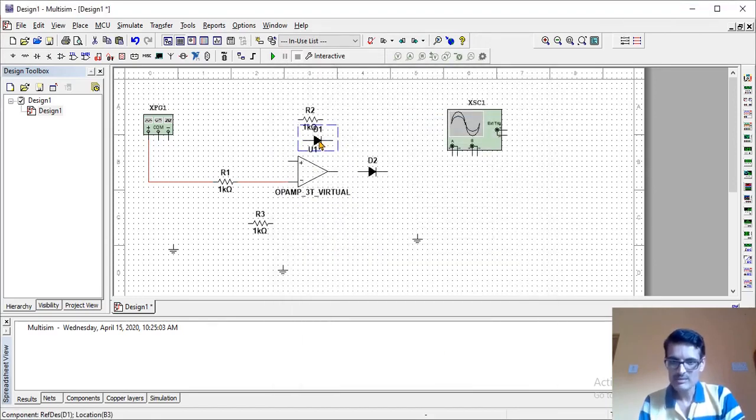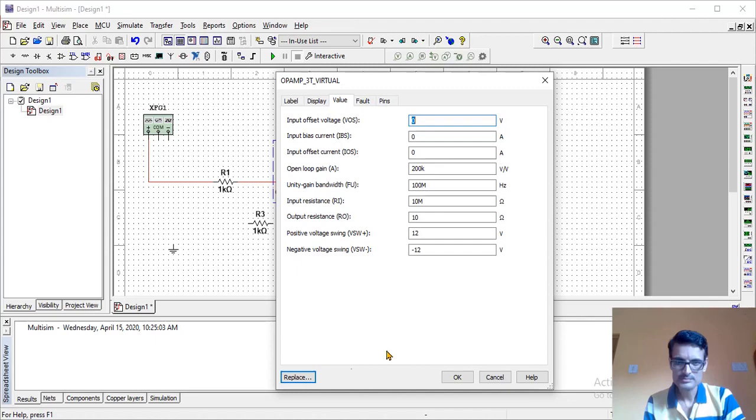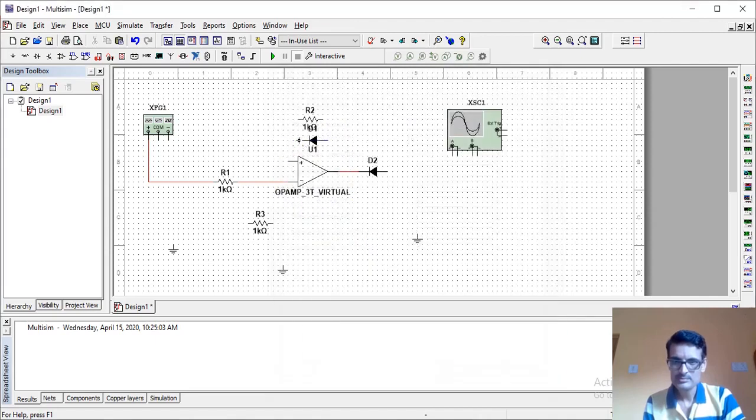I'll reverse it so that you can place it anyways, no problem. But these two diodes should be in the same direction. I'll go with this. This to the inverting terminal. Same. So basically inverting amplifier, but with some additional diodes for rectification purpose, precision rectification purpose. I'll place it this.